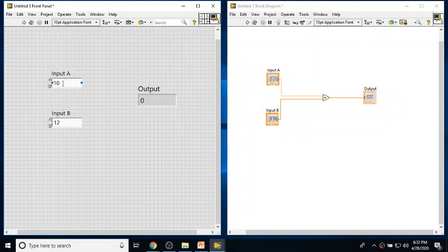So what I'll do is I can set some value. Once again, let me say 34, some random value, and I'll move my cursor here. Can you see I'm touching my run button and clicking once? You can see your code executes for a fraction of a second, processes the data, and shows the output. You can see there is no change on the block diagram. You will not see any changes on the block diagram, but on the front panel you can see the data are moved to the block diagram, get accessed, get manipulated, and the output is made visible on the front panel again.